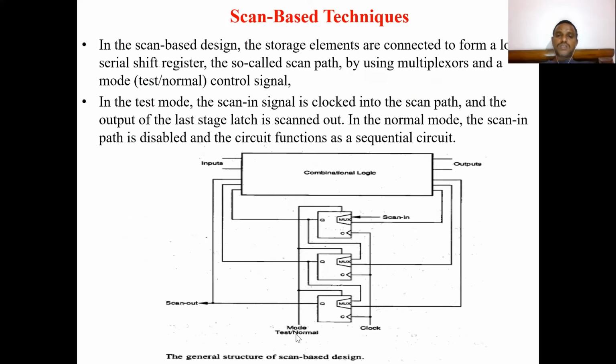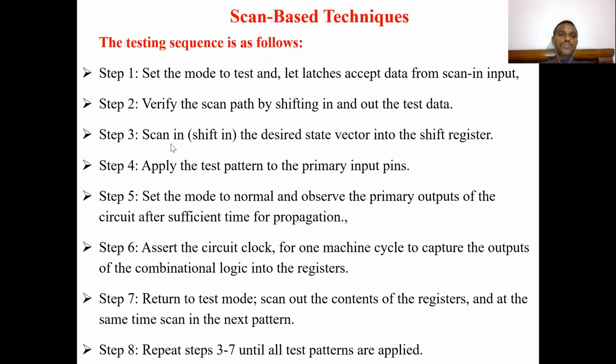So to test this circuit, first I have to take the mode of the control signal, that is the test mode. Okay, so that is the point. So set the mode to test. Let latches accept data from the scan input.